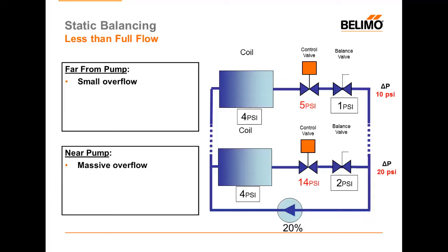You can see why static balancing can cause a lot of problems. We don't spend a lot of time with our system operating at 100% pump with our valves wide open. Indeed, most of the time we have our pump at a reduced rate and our valves are modulating through a mid-range position.